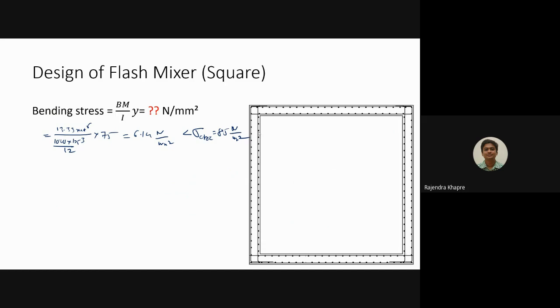Okay, that's why the circular shape is more recommended, but in some cases circular shape is not possible. In that case we have to go for the square only, because square and rectangular, they are very easy for construction. Special formwork is required for circular tanks, whereas for square tanks as such no special formwork is needed. Okay, सो इसका भी मैं फाउंडेशन नहीं ले रहा हूँ. इट्स अ बेसिक फाउंडेशन, नॉट मच टू डिज़ाइन, एंड rest is pretty simple as far as this portion is concerned.